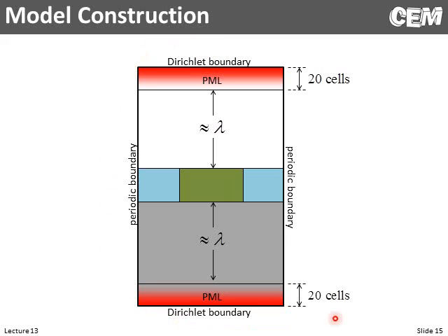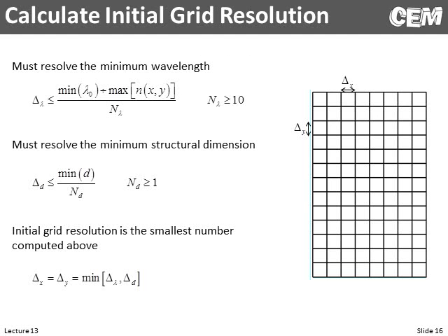So here's our overall grid strategy. This is the 60,000 foot level of what we want to do. But we still have to put numbers to a lot of this. So the first thing, what grid resolution do we need? And so I'll start off by saying that there is no equation that I can give you so that you can calculate the size of the grid and the grid parameters that'll work. All I can give you are some rules of thumb and things that work well, but the real answer comes from something called convergence. We'll talk more about that in the next lecture, but the short answer to convergence is